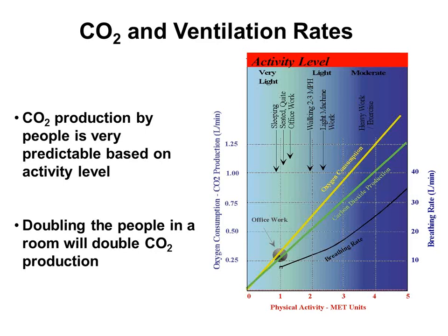But if you're doing a different job, where people are at a fitness center running on a treadmill or something, then the rules might be a little bit different. Just keep that in mind. The more active I am, the more oxygen I'm going to take in, hence the more CO2 I'm going to produce. It just changes some of the math on my controls. It doesn't mean I can't do the system. All right?